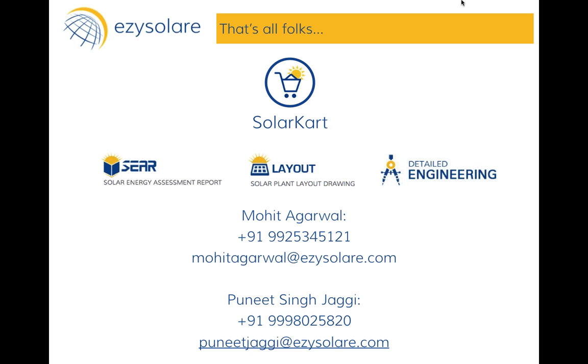What is the maximum available PR in India? The PR in India keeps on changing according to season. If you have got a high radiation, low temperature area, you can theoretically get a PR as high as 82, 83%, even better. If you have got a low radiation, high temperature area, then you can go to a PR as low as 75%. The PR which is typically guaranteed in India is in the range of 75 to 78%.